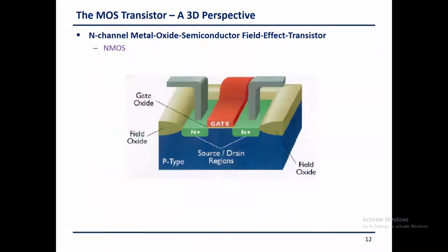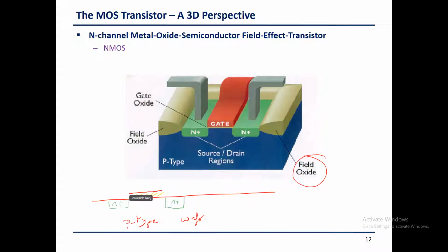So this is the transistor. Now that this is the transistor, we want to know what these layers are. If you see here, we drew for you that there is silicon dioxide. It's a field oxide. I have the wafer. The wafer starts as a p-type. All the wafer is p-type. Then for the specific transistor, I will have around it the source and the drain. And then I will have the thin oxide layer for the T-ox, and then I will have the gate, which is poly material in old times. Now it is again metal.